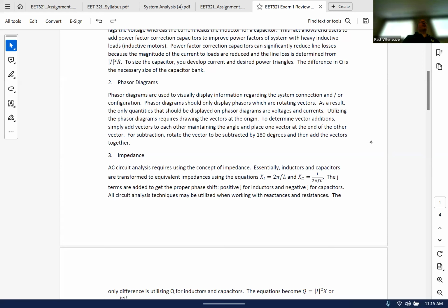If you can do phasor diagrams, that will really help you with three-phase systems, because with delta-Y circuits, when I'm measuring VAB, which is my line voltage, I can see that it means VA minus VB. I don't know about other conventions, but when we use this convention here, VAB means you put your red lead on the A and your black lead on the B, which is the same thing as saying VA minus VB, right?